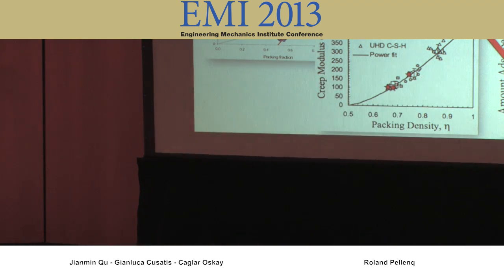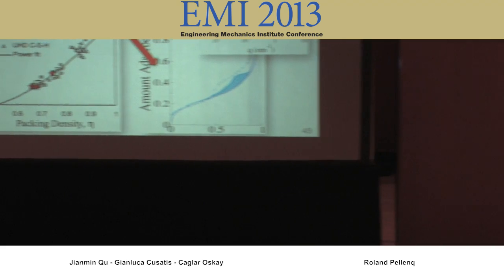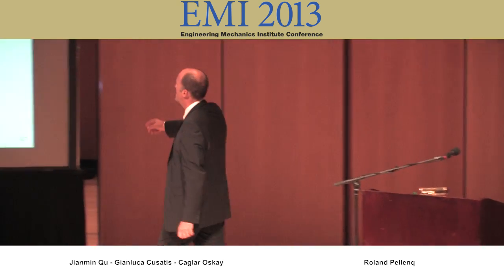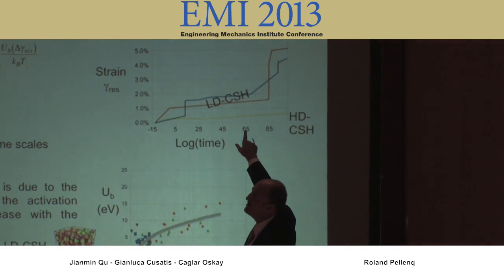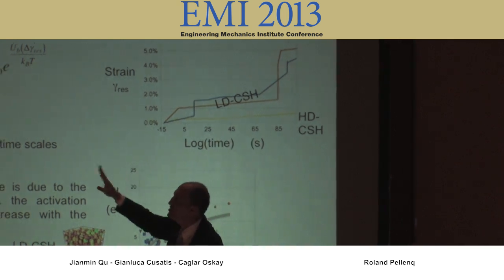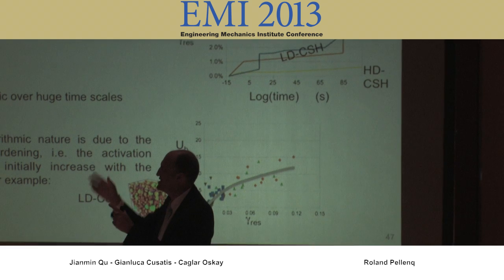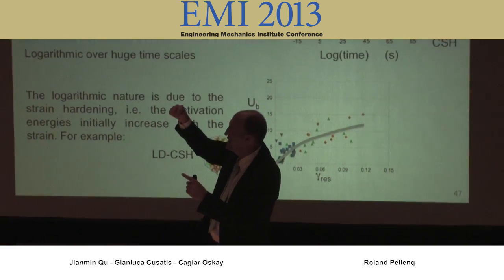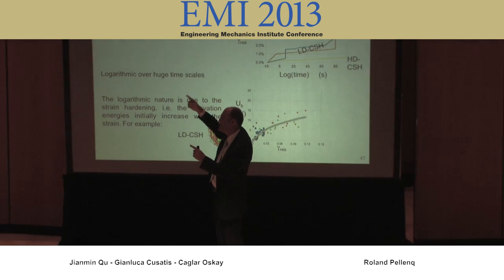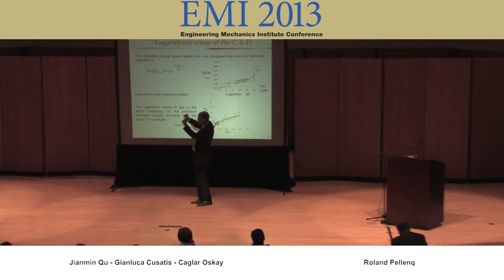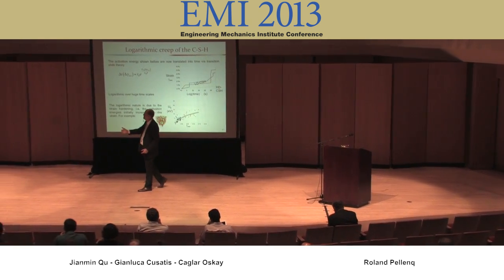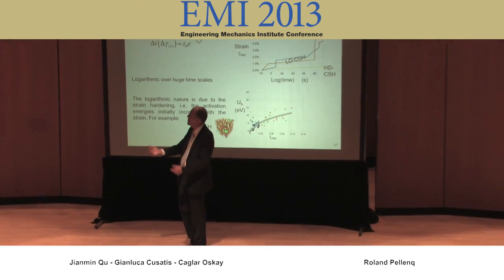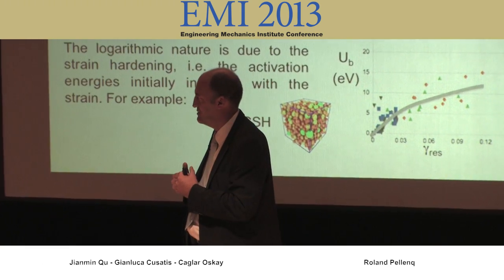So that's a way to actually bridge up toward very long time scales. If I go back to the creep thing, you see this curve here. This is in log of seconds, but I tell you 65, if you take exponential of 65 seconds, it starts to be a long time. So we run kind of short simulation, but you plug onto this the TST, providing that you hope to have a good description of the energy barriers. This is the way today to bridge towards very long time scales from short simulation, if you like.